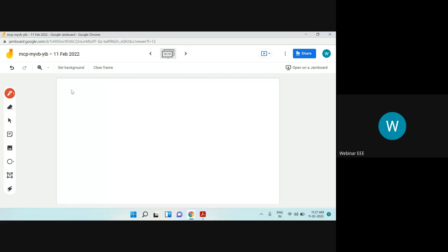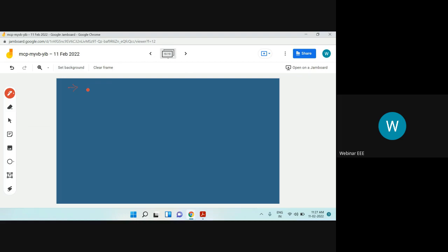Coming to the next bridge, Anderson's bridge. Anderson's bridge is very important, which is the most accurate bridge of all for measurement of inductance. It is a 5-point bridge. If you observe the notes, in every bridge there will be 4 points, but here it will be seen as a 5-point bridge. At the place of the galvanometer, there will be one more capacitor connected.